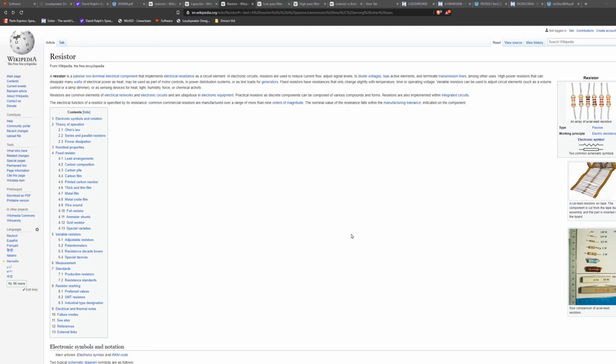And if you're doing a system that's several hundred watts, it may be worth running a simulation or solving the circuit using the Kirchhoff current law and Kirchhoff voltage law rules, or selecting an oversized resistor and not worrying about it.